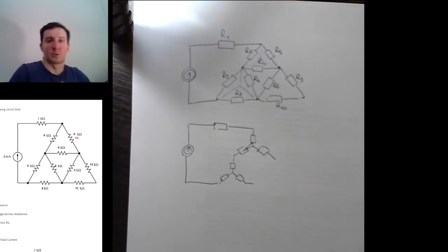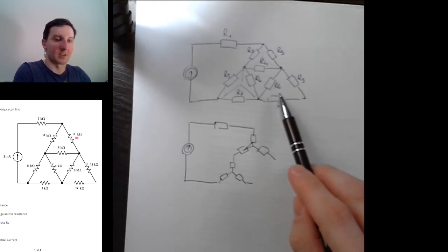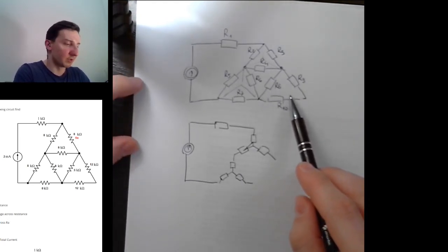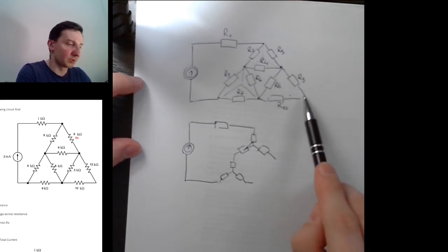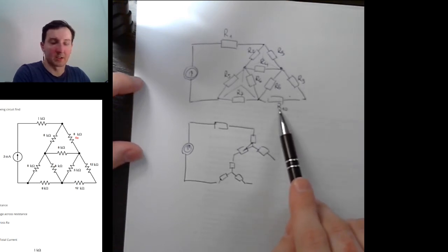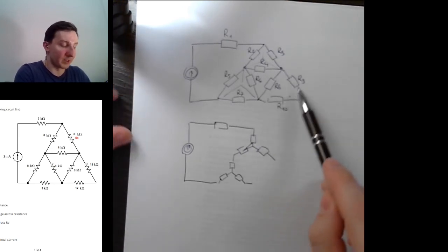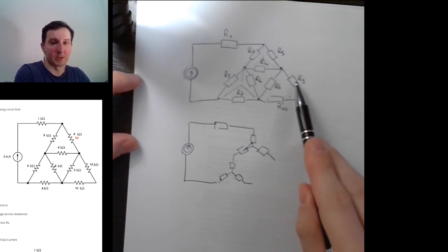What is important to notice is that this isn't a triangle like the 2 previous ones, because it doesn't have a node right here. These 2 resistors, R9 and R10, are connected in series, so we can simplify them by calculating the equivalent resistance, just by adding these 2 resistances.